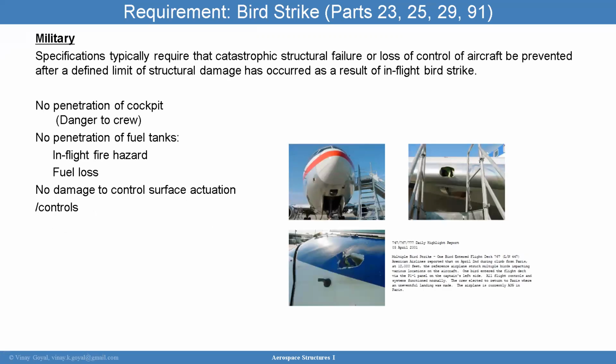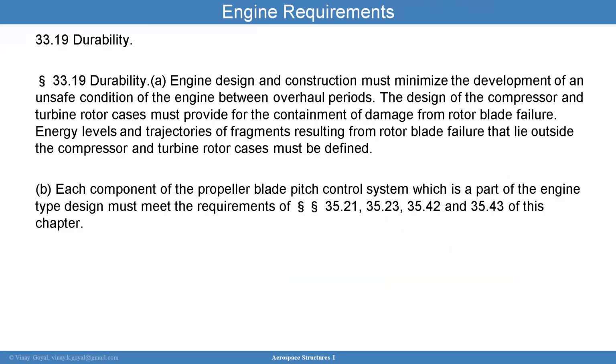For military, you're looking at no penetration of cockpit. You're looking at no penetration of fuel tanks because of potential fire hazard and no damage to control surfaces. Those are the main specs.